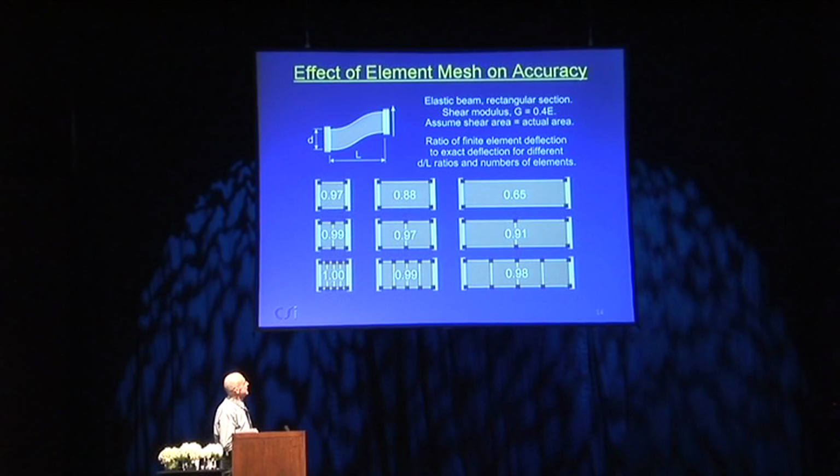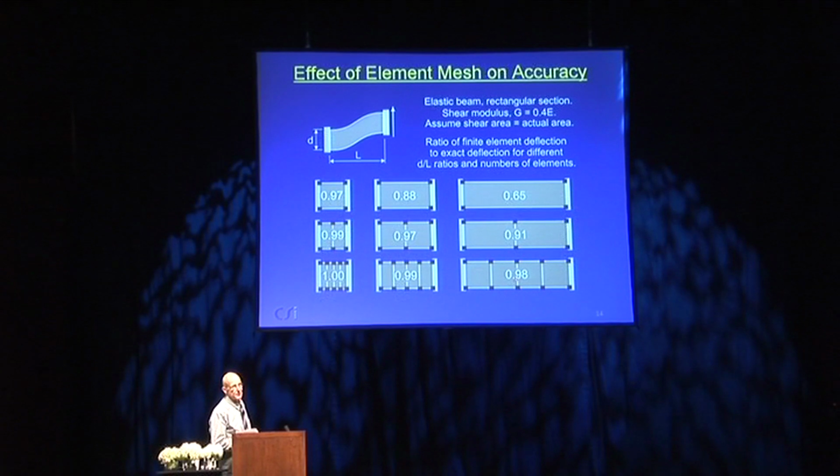If you look at what is going to be a pretty slender beam for coupling beams, a single element would not be accurate enough in terms of displacement. This might be, although it's a little questionable, but even here, 4 elements is ample for picking up the elastic stiffness. So that gives you an idea of how accurately the element can capture the elastic stiffness, even though it has constant curvature.